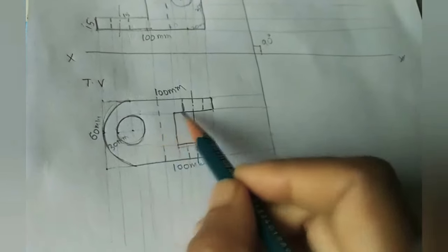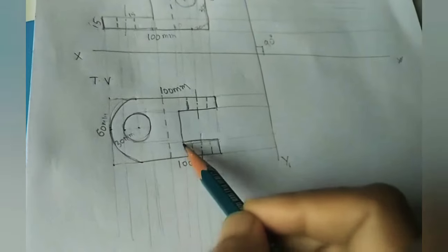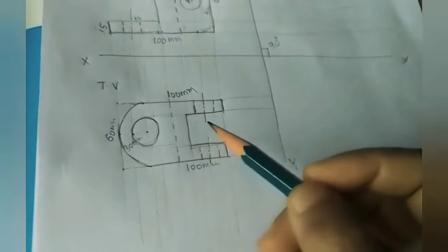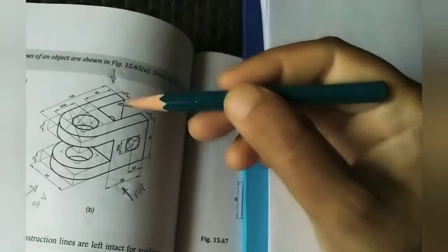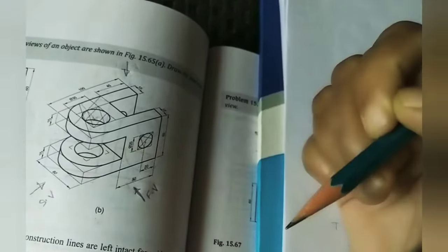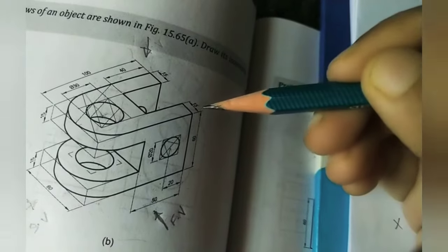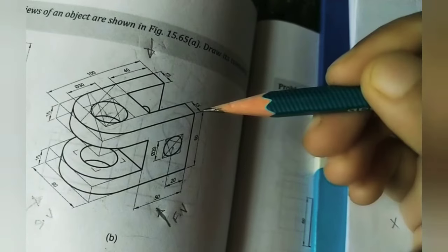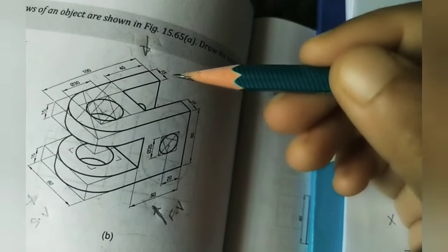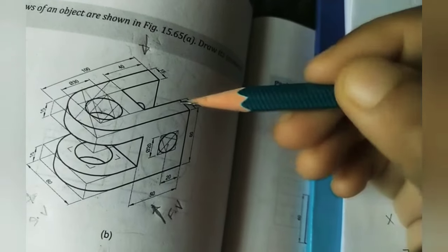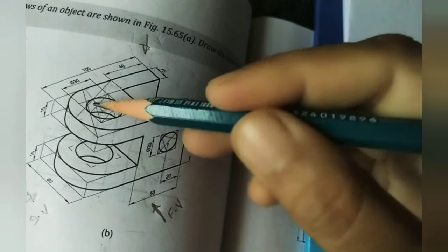Here, if you do this, these are coinciding with this gap. Let us check how much the width of this gap is. As we know, the diameter of the circle is 30 mm. Let us check this gap from the top view. From the top, this is, as you know, 60 mm. This is 15 mm, 15 mm. Add these two values, 30 mm. 60 mm minus 30 mm is also 30 mm, this gap. This is also 30 mm.